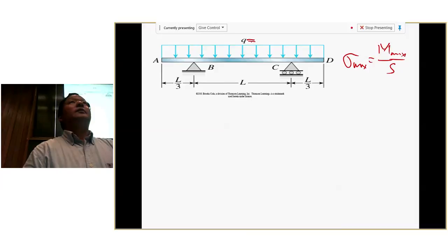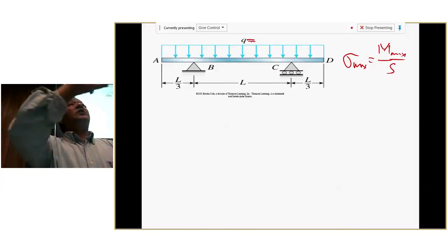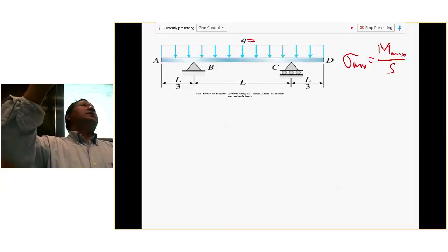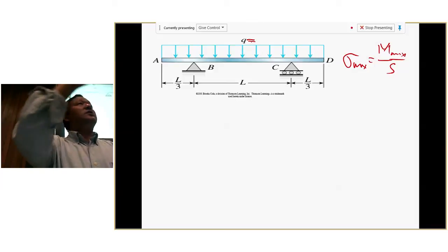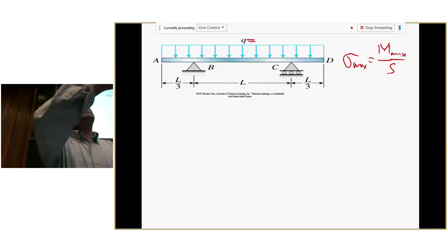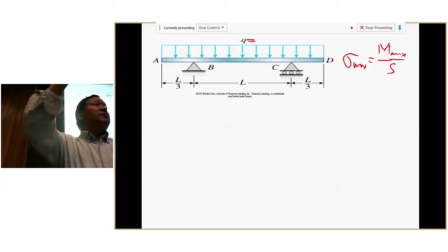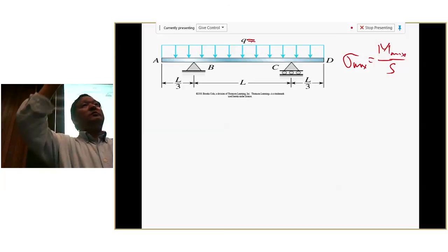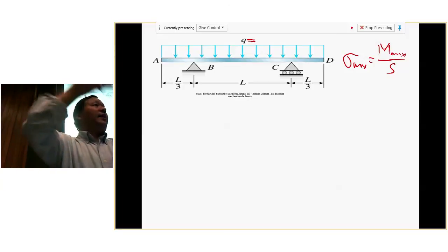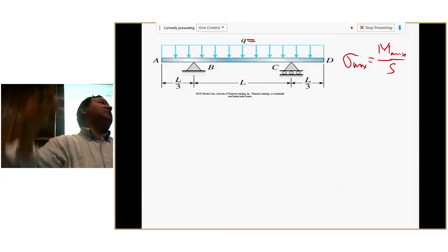Or you can come to me, we can talk about one. Basically, non-uniform is similar. It's just mathematically, when you calculate the total force, it's not this length times the magnitude anymore. You accumulate, so basically this minimum, maximum, you combine half of it, and then you calculate the total value.